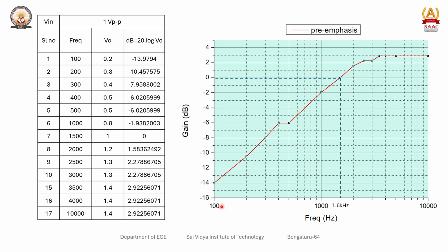On the semi-log sheet, the frequency I am going to start with is 100, and the last frequency in this first column of frequency is 1000, that is 10 divisions. So here you can observe the values of frequency versus gain. On the y axis I have considered gain, and on the x axis I have taken frequency. That is nothing but a log scale on the x axis and a linear scale on the y axis. Now you identify the points where you want to plot.